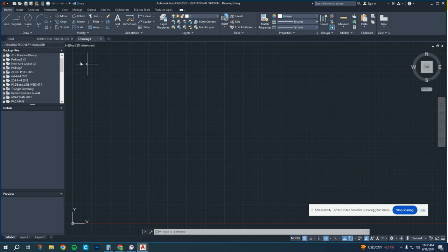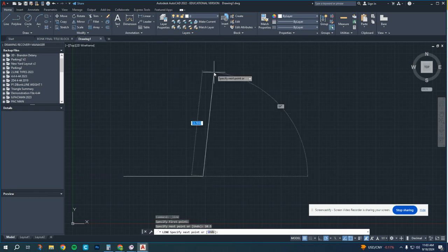Now we're just going to be drawing with lines at first. You're going to click somewhere in the bottom left quarter of the screen so you can start to drag a line. You're going to see a green dotted indication that you're at 0 degrees, or straight horizontal, and you type in the number 10.5. Hit the enter key, and it's going to make a 10.5 inch line,